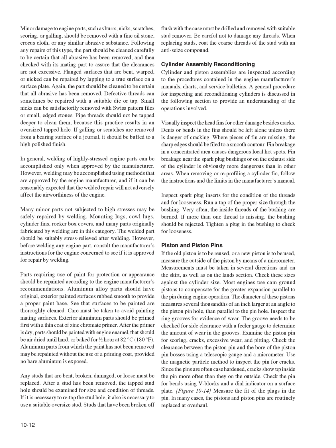Visually inspect the head fins for other damage besides cracks. Dents or bends in the fins should be left alone unless there is danger of cracking. Where pieces of fin are missing, the sharp edges should be filed to a smooth contour.